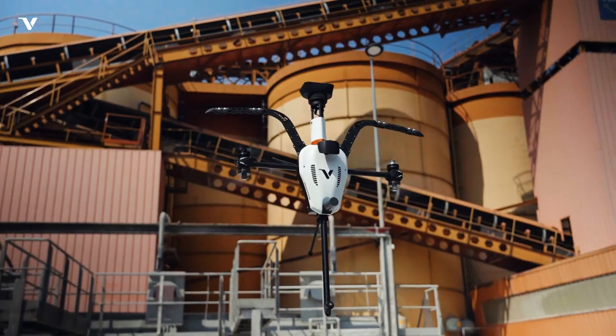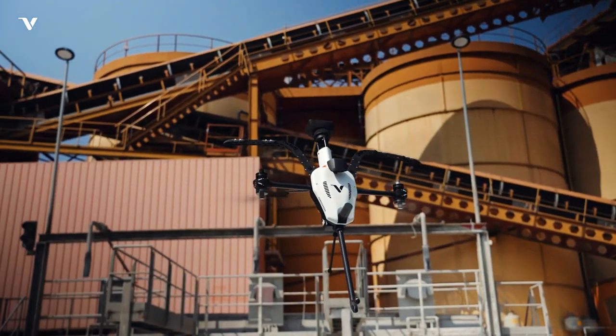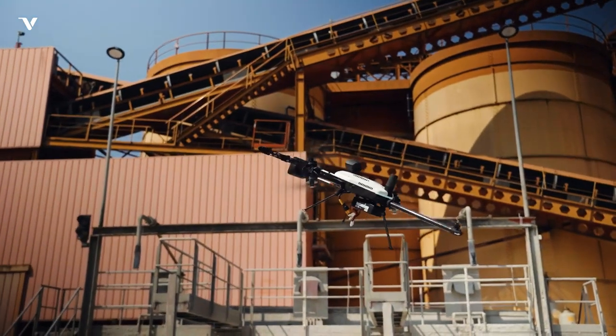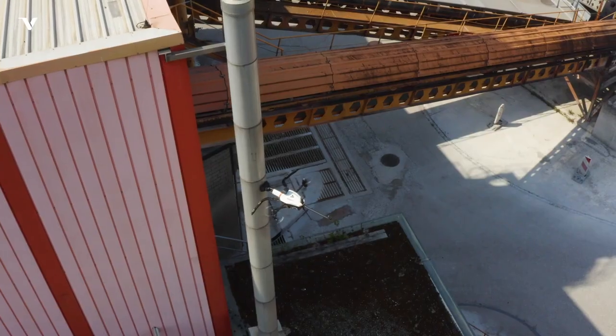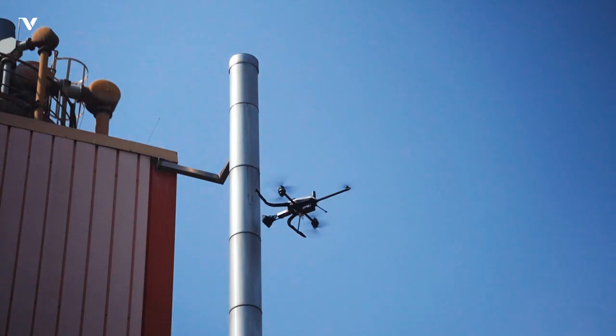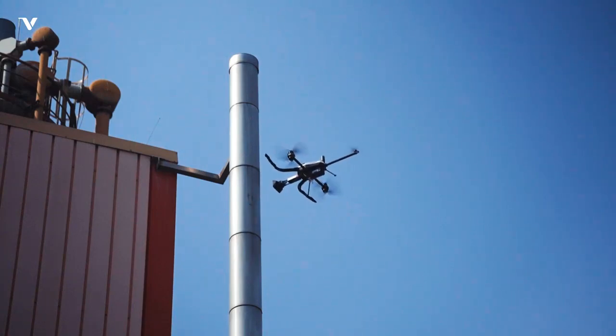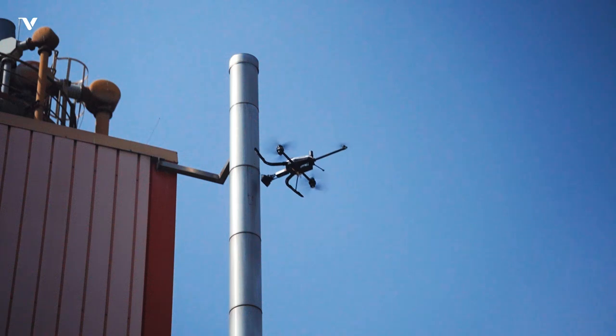Let's also talk about the general limitations of the pulse eddy current technology. This applies not only to our pulse eddy current, but to all pulse eddy current sensors out there. One is that it is a screening tool, so it's not the best tool to find pitting type defects, but it's the perfect tool to find general corrosion under insulation. Furthermore, it cannot discriminate between near side and far side defects.